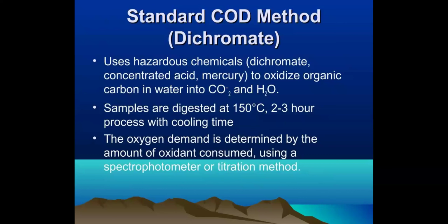The standard COD method uses hazardous chemicals. We can measure the concentration of the hazardous chemical content in the water or wastewater. Right? The dichromate, concentrated acid, and mercury oxidize the organic carbon in water to CO2 and H2O.